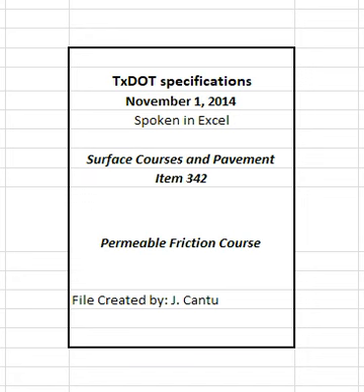The engineer will obtain at least one sample of the tack coat binder per project in accordance with Tex-500-C, Part 3, and test it to verify compliance with Item 300, Asphalts, Oils, and Emulsions. The engineer will obtain the sample from the asphalt distributor immediately before use.